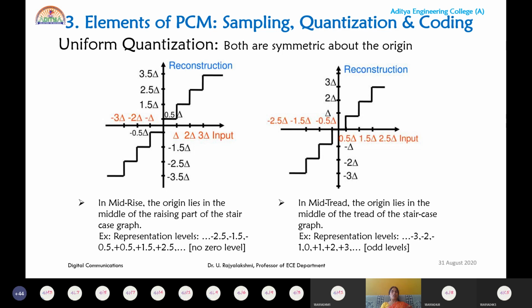Please observe the reconstruction levels for mid-rise. You don't have the 0 level. It only consists of levels like -2.5, -1.5, -0.5, 0.5, 1.5, 2.5, 3.5, and so on.